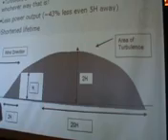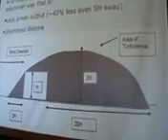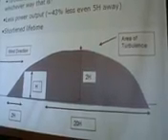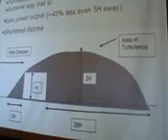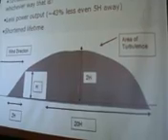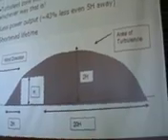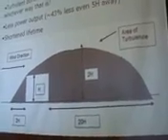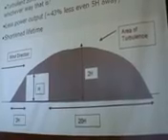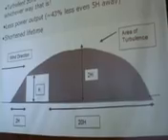Okay? Another example of that is if you've got something like a house here of size H, this is the area of wind that's affected by that turbulence, up to twice the height and 20 times downwind. It can be a really big effect. So in choosing where to put a turbine, you want to try and avoid any obstructions like that, or put the turbine up above them, a bit higher up.